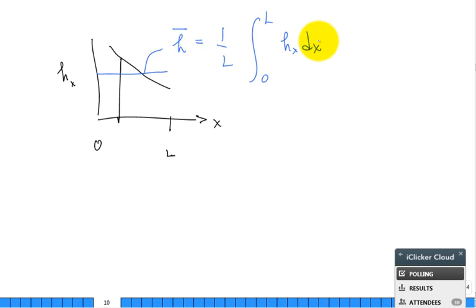True or false? Didn't we do that? Yeah, we did that. Likewise, you can do the same with the Nusselt number, the average Nusselt number, 1 over L, the integral from 0 to L of the local Nusselt number dx. So I don't make a big deal of it because there's so many correlations that you can get confused. But just think of it. If I've shown you an equation for a local, there's probably an equation for an average.